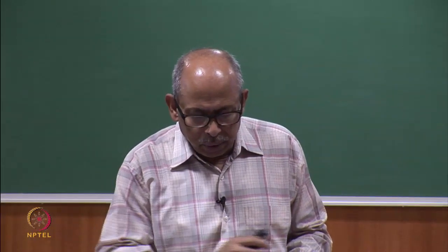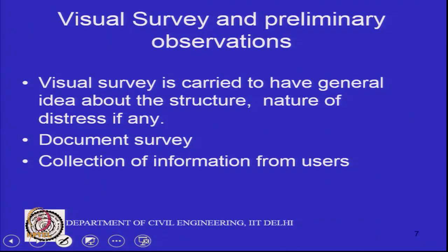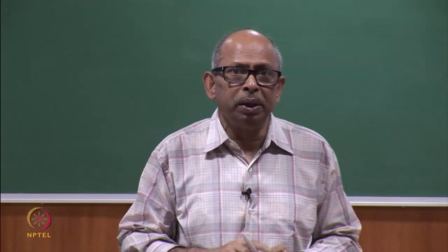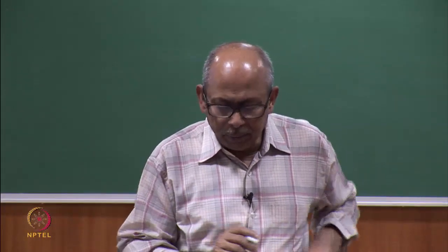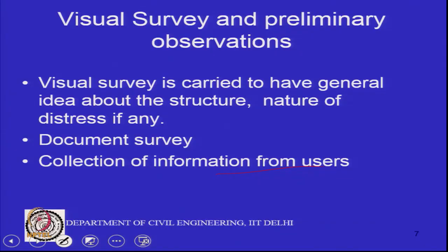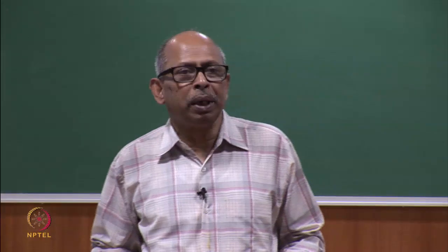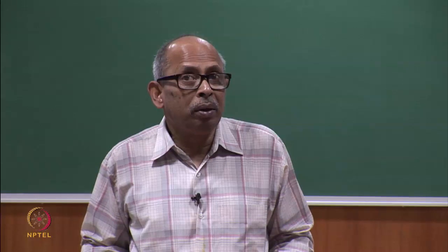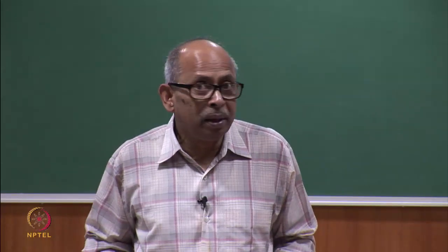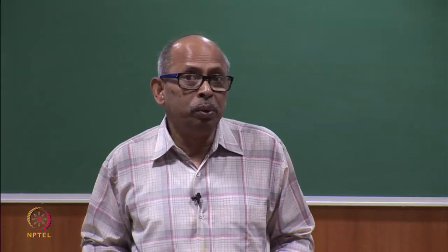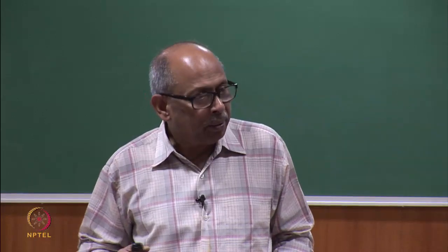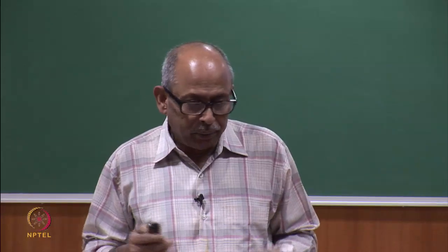So, visual survey is carried out generally to have a general idea about the structure, nature of the distress. Document survey means drawings, etc., as I mentioned last class, and also sometimes collecting information from the user, which in that case could be simply the person who is a security personnel or people who do some maintenance and operation works, maybe lift operators and so on. So, you can find out some information from them as well, and all this goes into your